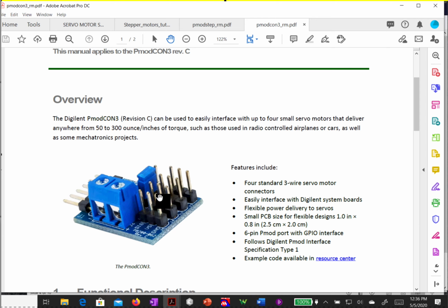So we provide 3 signals to the servo motor. We have power, ground, and a signal, and you see right here we have signal, VSS, power, and ground. Those are the 3 signals we provide to the motor. And so we'll be able to connect 4 motors with this, and we have 4 logical inputs that we're going to drive. Those could be output compare, or they could be using the timers, doing them in sequence.